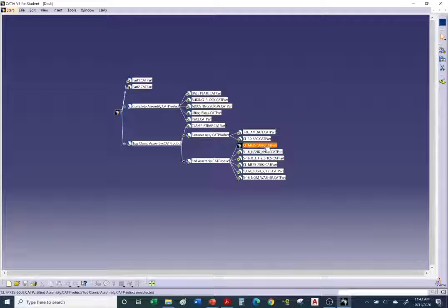Okay, so anytime you see red, it tells you that, hey, we lost this file. We can't locate it. If you see white, everything was linked. Most likely in your flash drive and the folder in your flash drive, it linked it. If it's black, it means it's dormant. That's when you have cache mode on. Remember we talked about cache in a previous lecture? Okay, so this is red, letting me know it can't find it.